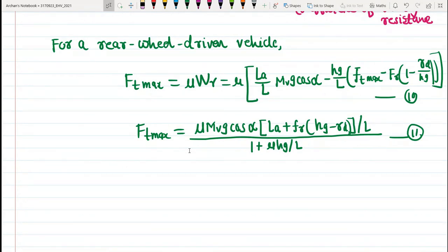In this case, a tractive torque on the drive wheel would cause the wheel to have significant slipping on the ground, and the maximum tractive effort on the driven wheel depends on the longitudinal force that the adhesive capability between the tire and ground can supply, rather than the maximum torque that the engine can supply.